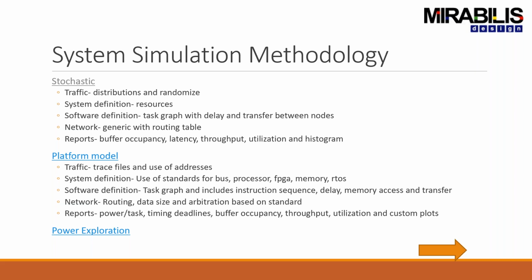So now, what is the difference in terms of the statistics? One is obviously you're getting far more accuracy. The second thing is you might have very specific profiling results that you might be looking at. For example, I might be looking at watts per memory access. So if I'm doing 300 memory accesses, how much is the power consumed? Versus if I'm doing everything locally with a hardware accelerator and I'm using a block RAM, versus I go get the data from an external DRAM. How does that change my performance, or how does that change the power profile of my system?